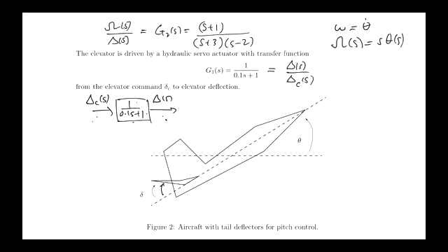All right, and then that goes into this unstable transfer function that has one zero at s equals minus 1. It has one pole at s equals minus 3, that's stable, but it has one pole at s equals plus 2, right, which is unstable. Okay, so overall, our plant, if you like, the thing we're trying to control, is unstable.